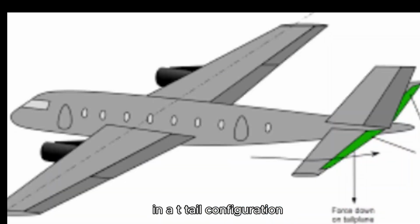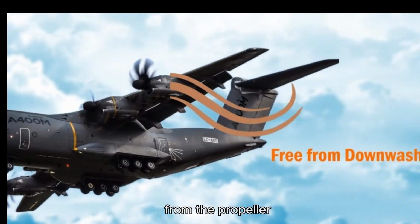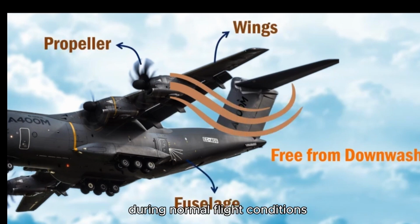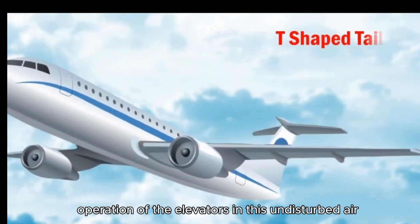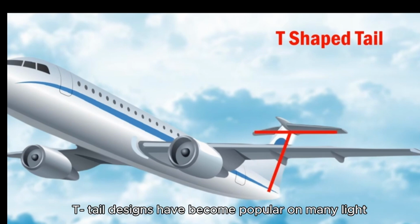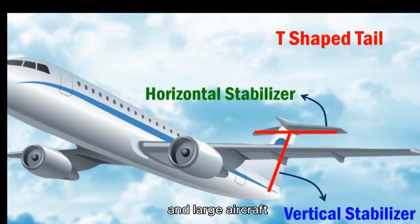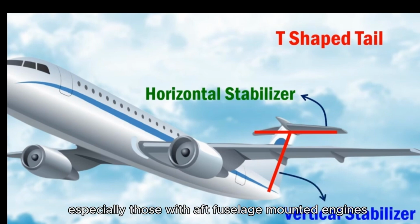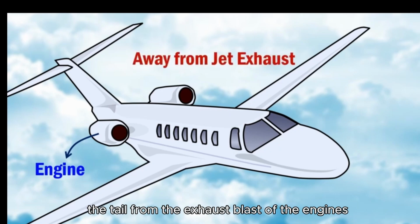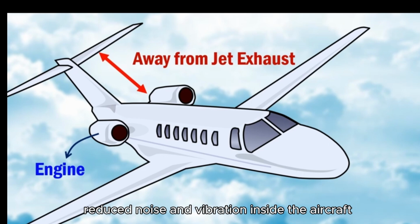T-tail. In a T-tail configuration, the elevator is above most of the effects of downwash from the propeller, as well as airflow around the fuselage and/or wings during normal flight conditions. Operation of the elevators in this undisturbed air allows control movements that are consistent throughout most flight regimes. T-tail designs have become popular on many light and large aircraft, especially those with aft fuselage-mounted engines, because the T-tail configuration removes the tail from the exhaust blast of the engines. An additional benefit is reduced noise and vibration inside the aircraft.